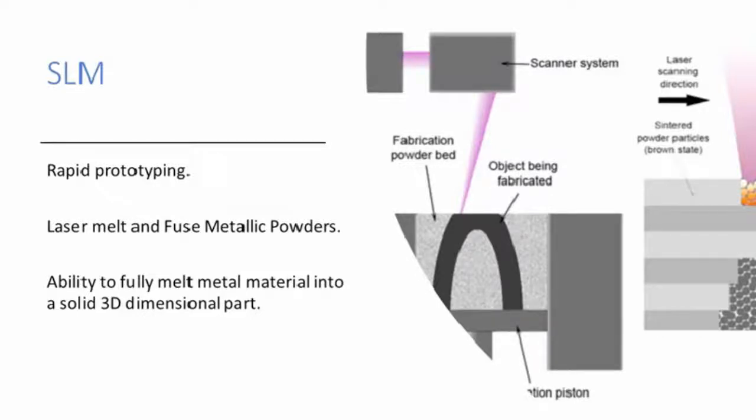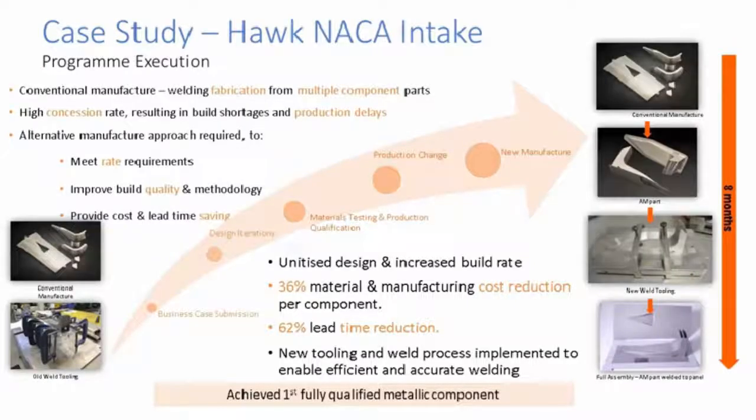SLM allows parts to be built additively to form near-net-shaped components, rather than by removing waste material. Some of the materials being used in this process can include copper, aluminium, stainless steel, cobalt chrome, titanium and tungsten. Generally, for the material to be used in the process, it must be in its atomized powder form. Specific applications in aerospace include air ducts, fixtures or mountings holding specific aeronautical instruments within commercial and military aerospace.